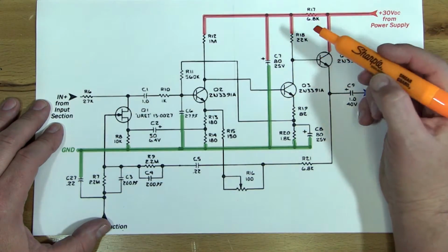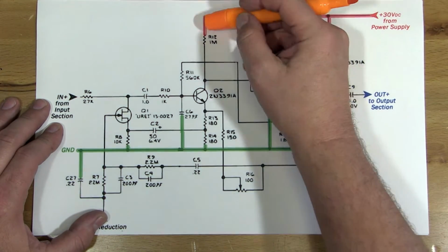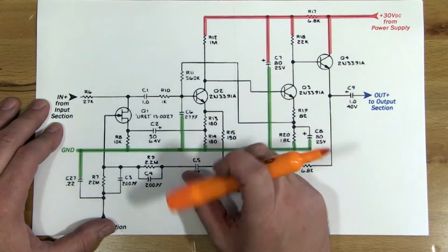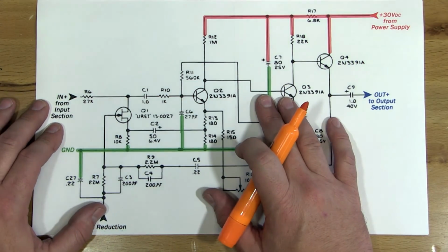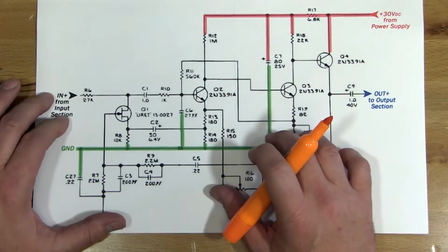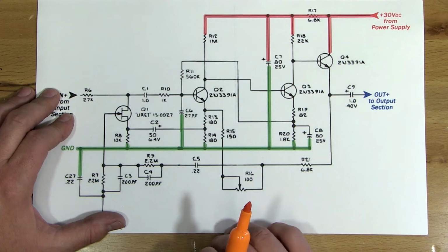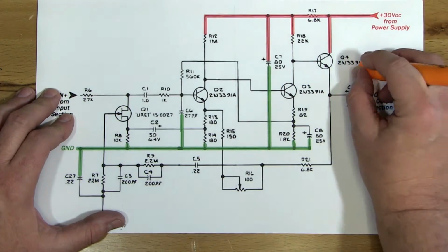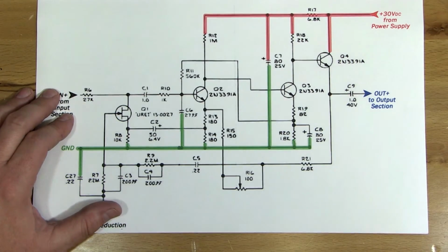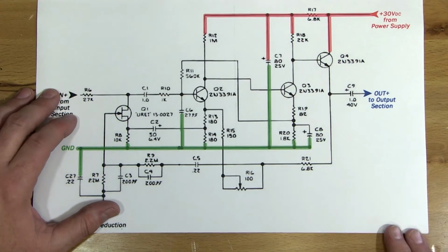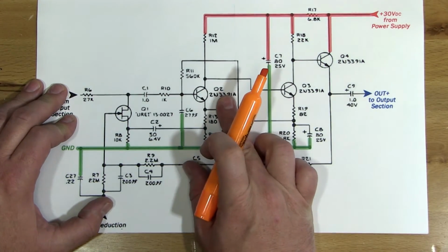And we have positive voltage and ground here. So the DC current path is going to go from positive voltage to ground. I don't care about direction here. So you can draw electron flow, you can draw current flow, conventional current flow. Either one is fine. If you had a negative voltage, you might be drawing to that. So the current has to be able to go from a more positive to a more negative. That could be positive and ground, that could be positive and negative, that could be ground and negative, whatever the case might be.